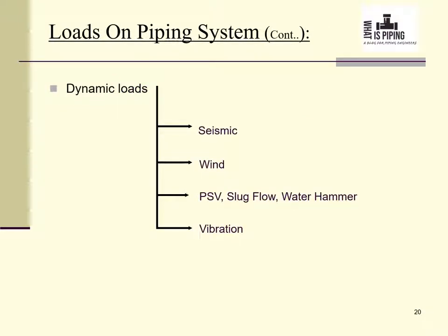Let's move on to dynamic loads. Dynamic loads vary along with time. So these loads are time dependent. Examples are seismic, wind, PSV, slug flow, water hammer, and vibration. At different instant of time, the values will be different for this kind of loads.